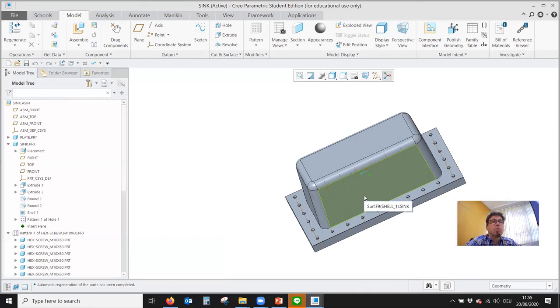The second thing we talked about was using patterns where applicable. And in mechanical engineering, patterns happen quite a lot. And again, there my message was model wisely. Think about the complete modeling steps right to the end before you start really making CAD models, so you can identify potential for clever modeling. For example, as I did it before, make the second part as a copy of the first one. So already I don't have to model the pattern 2 times. And then especially placing fasteners on this pattern.